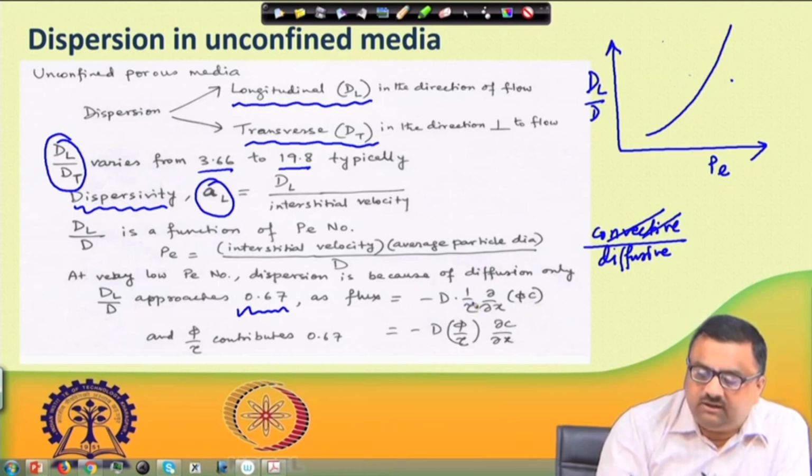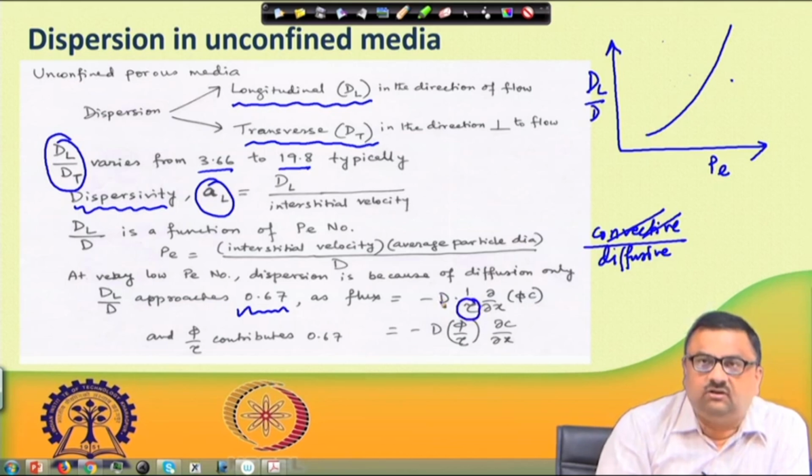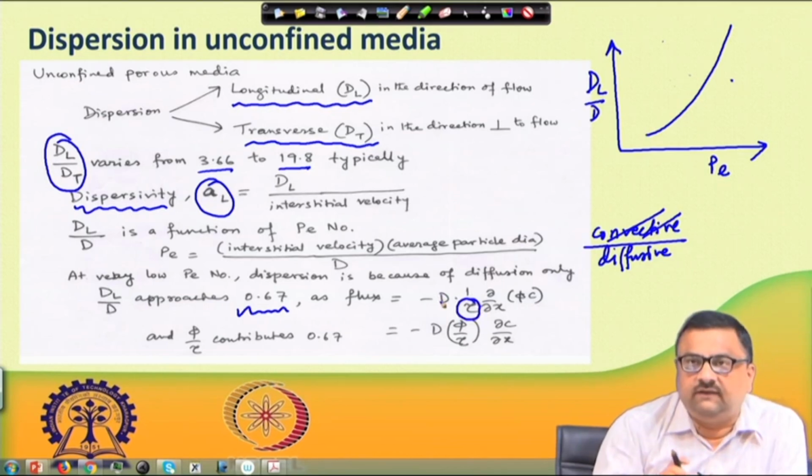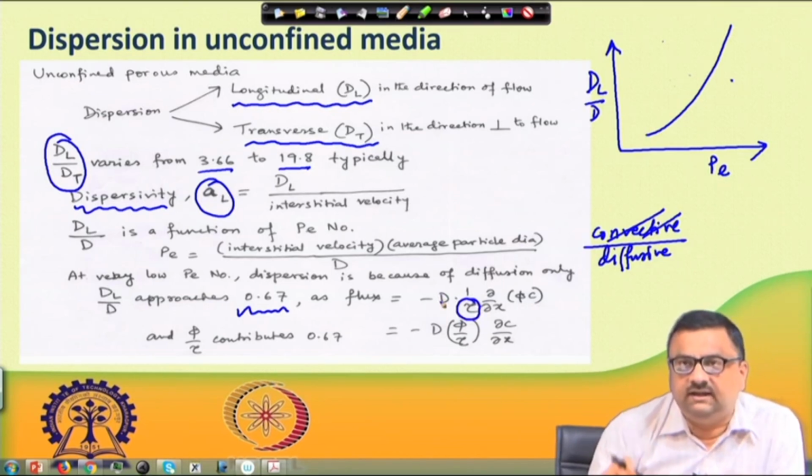And then what they had done is, they divide this bulk diffusivity by a factor known as tortuosity, to account for the fact that here the diffusion is taking place inside a porous medium, not in a beaker, it is not a free diffusion.